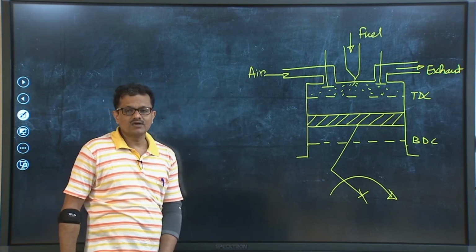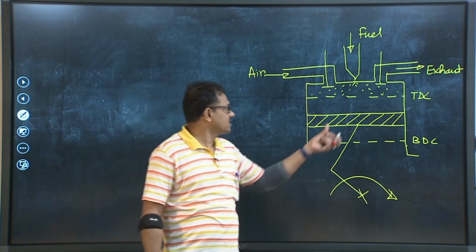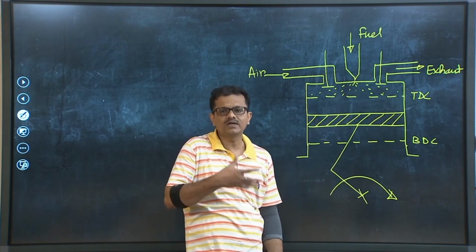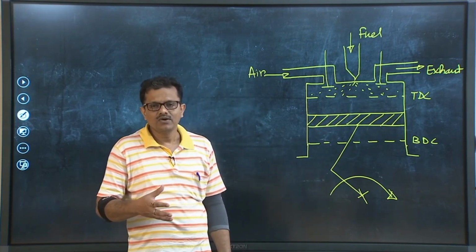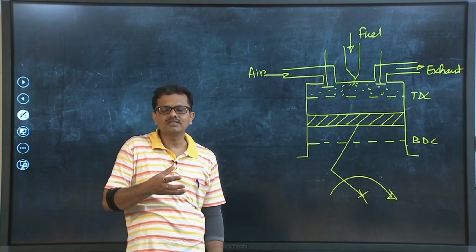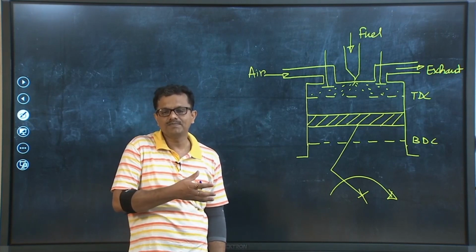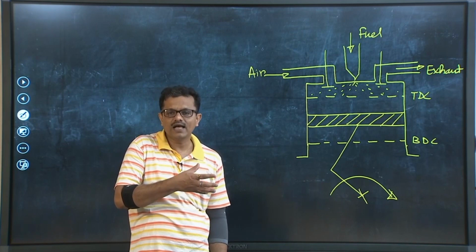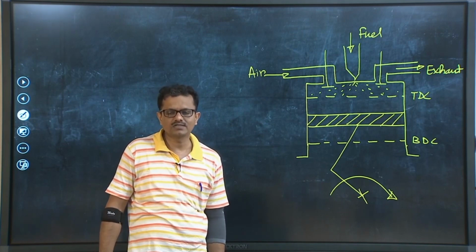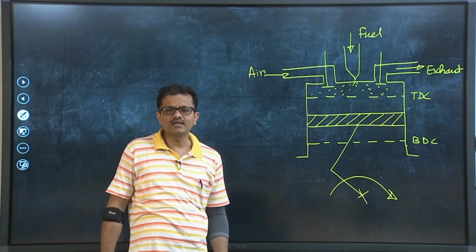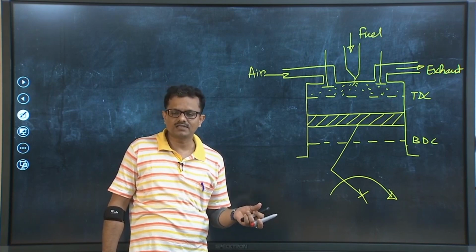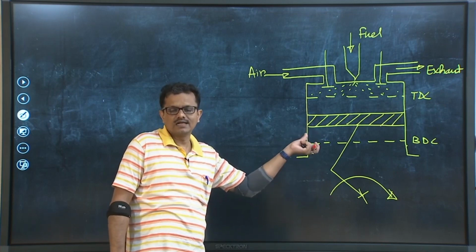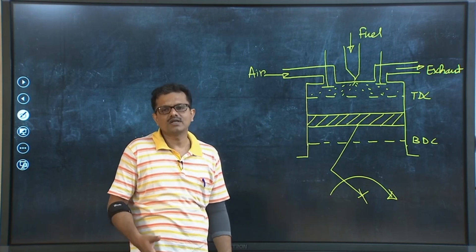One important part is that in the context of the Otto cycle we discussed the combustion process, which is very important, as it provides a certain amount of heat to the system. When we represented that process in the PV and TS planes, particularly in the PV plane, it was a constant volume heat addition. But can we again represent the combustion process by a constant volume heat addition in the PV plane for this cycle, that is the diesel cycle, or not? That is what I would like to discuss briefly here.